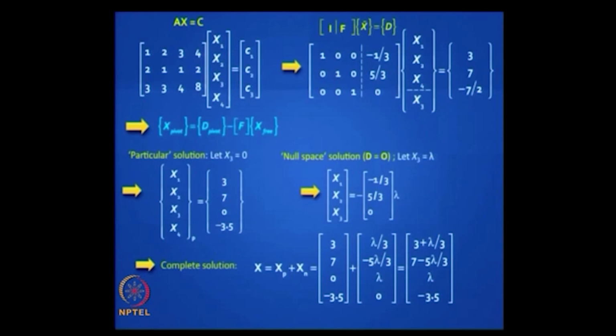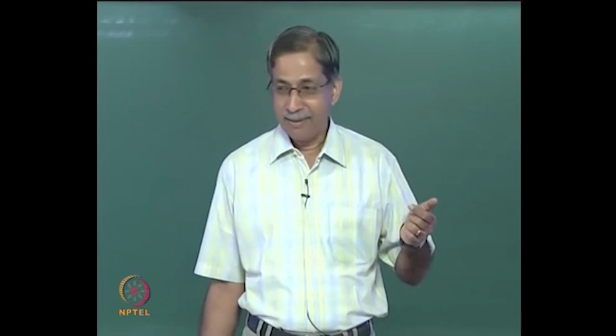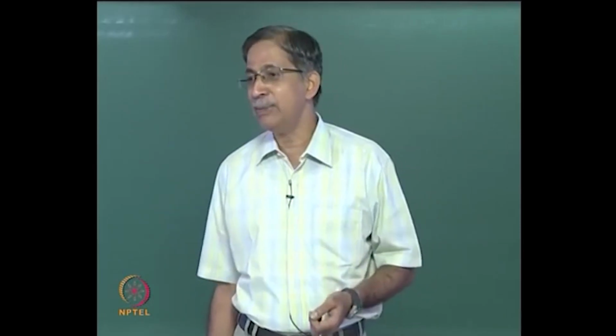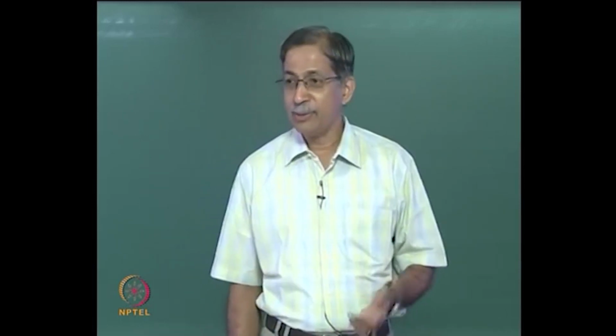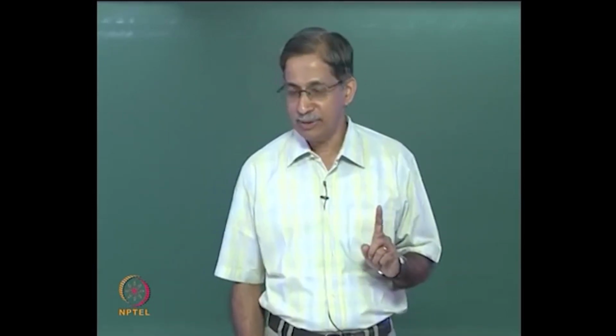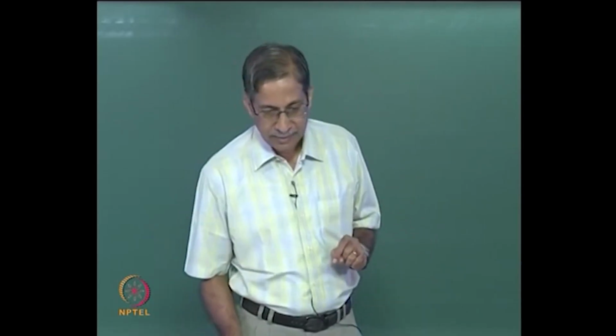Okay, we don't even do this. We do it when? We wanted to find displacements in statically indeterminate structures after having analyzed it. Remember, there we chose lambda to be 0, so we didn't waste time doing all this. Okay, because you need any statically admissible solution to apply the principle of virtual work.